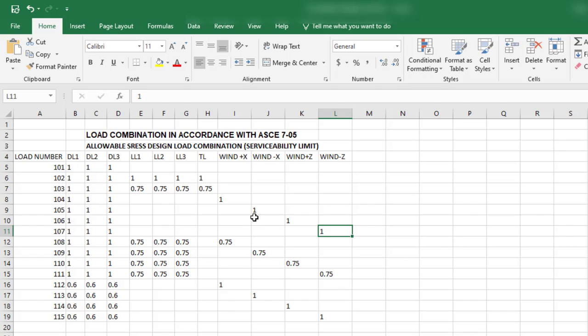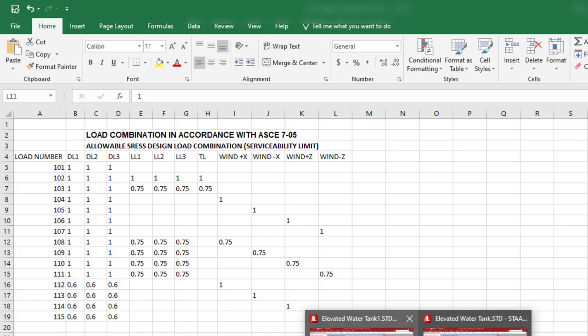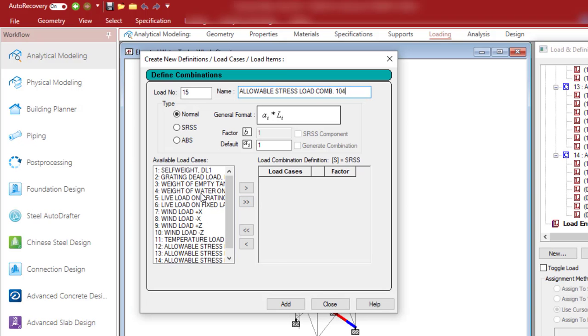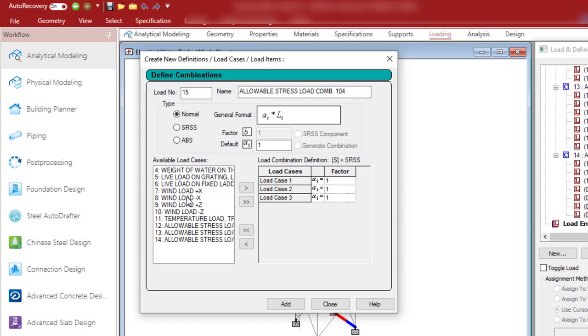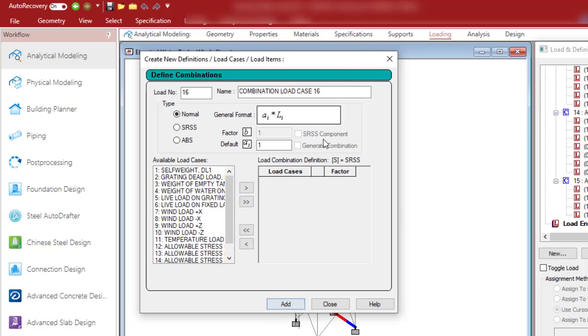We want to know the behavior of the structure when wind is coming from each direction at different times. That's the idea. So we come here again, all the dead load factor 1, then wind load in X direction. Now click add. This one is 5.